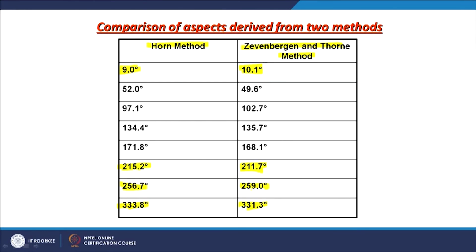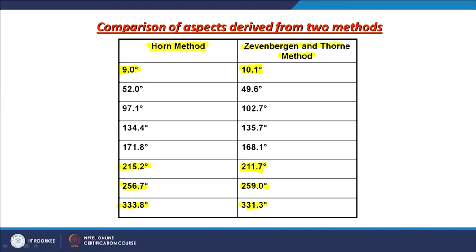So, definitely each method will have its own advantages and disadvantages. Now, which one to choose? As when we discussed the slope part, we said that in ArcGIS software and many other softwares, the Horn method has been implemented. So, in the case of aspect calculation also the Horn method has been implemented. But if somebody would like to use the other one, then tools are also available, may not be within that software, you have to search the net.